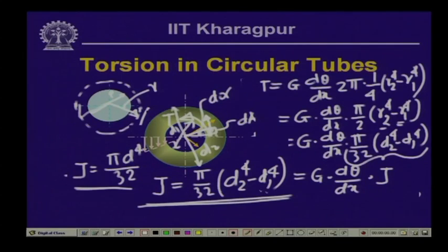So, this is a similar expression, and you can visualize that from the whole section we are removing the central part. In a solid circular shaft, because the shearing strain and stresses vary from the center to the outer periphery, being 0 at the center and maximum at the outer periphery, if we remove the material from the central portion, the maximum stress still occurs at the outer periphery.